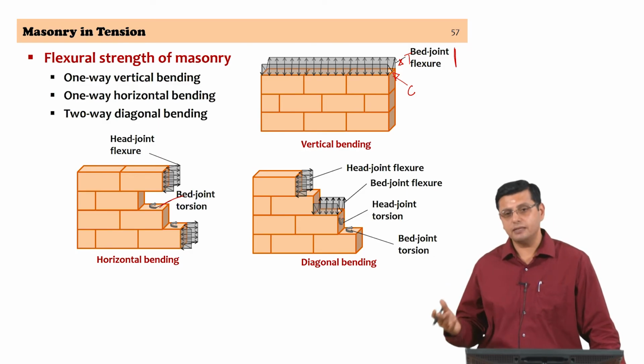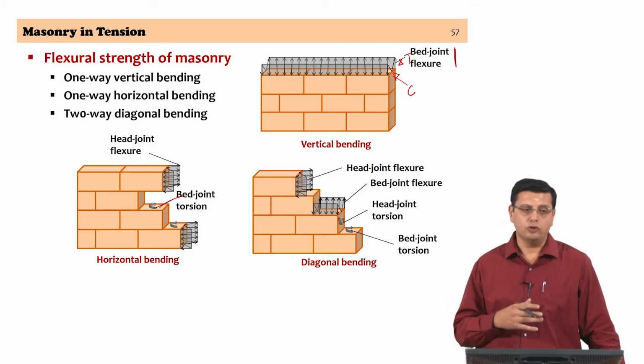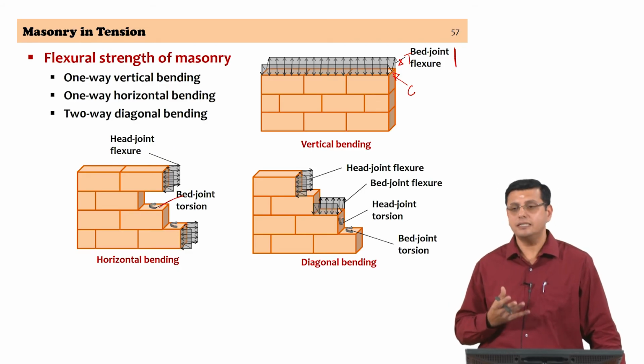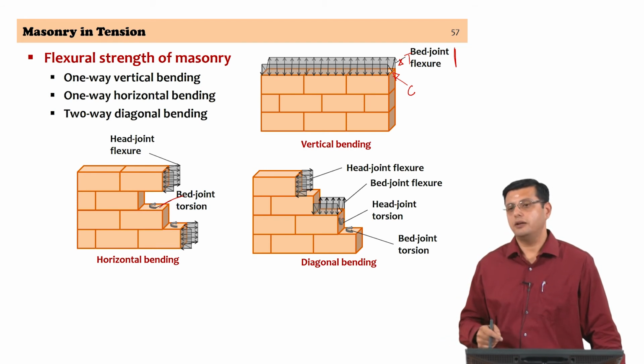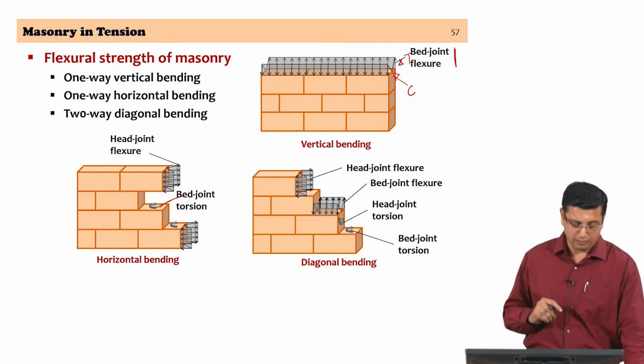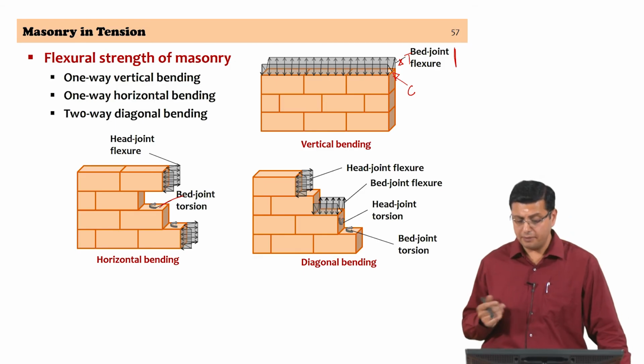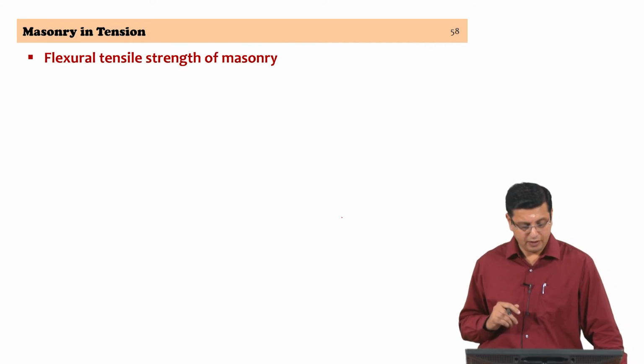However, we make simplifications in design, but if you are doing an assessment and if you are doing a detailed assessment of masonry strengths, it is essential to understand that you are going to have different values for each of these actions and each of these failure mechanisms in the same masonry wall itself.